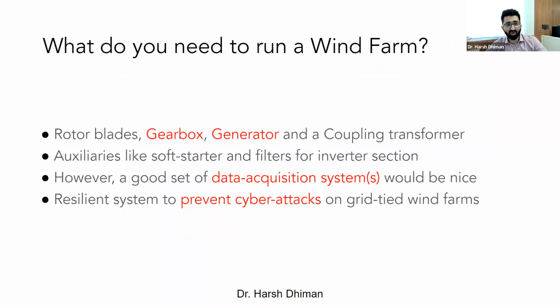Then you need a soft starter, because essentially when the turbine starts, it would behave as a motor. Generator and motor operation are dependent on slip speed. If you're using an induction generator or an induction machine, the slip would decide your operation in terms of motoring or generating. So initially the machine behaves as a motor, and then gradually, when the torque received from the incoming wind speed is high enough, it starts generating.